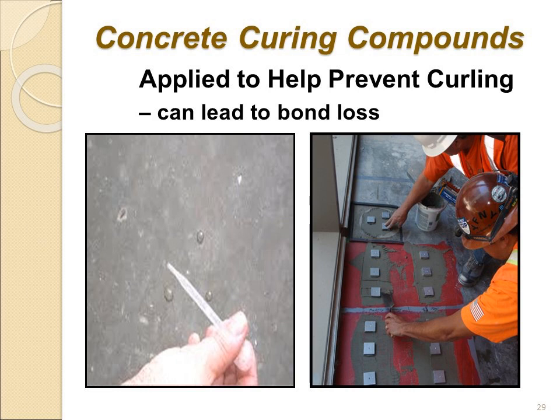In order for it to bond to it, we need some type of absorption. On the left-hand side, you see someone using a little droplet in order to determine whether the concrete slab is absorptive. For those of you who are not aware, there's a practice in the resilient floor industry that was designed through ASTM, and it's ASTM F3191, and that's a literal practice that you can use to establish a criteria as to whether a slab is absorptive or not.